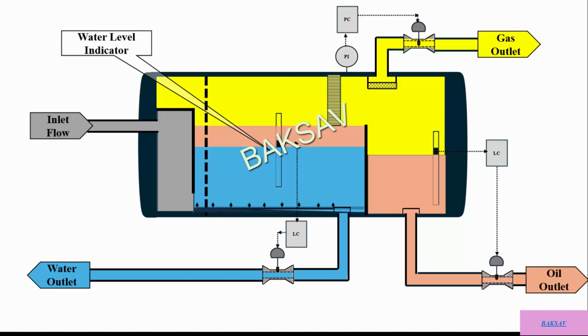This level indicator shall be configured in such a way that it doesn't react to the common level change of the water section level but reacts only to water level changes. Usually that is achieved by selecting an indicator with a level-measuring floating element made from material heavier than oil but lighter than water. In this configuration, the level indicator measuring element drowns in oil but floats on the oil-water interface and reacts once this interface level changes.